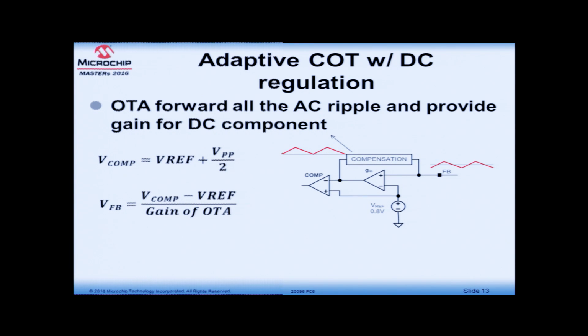In some of our data sheets you see a block named compensation. It is not actually a compensation; it is a low pass filter with a buffer. It is a capacitor, integrator and a buffer. To protect the IP, we named it the compensation block.